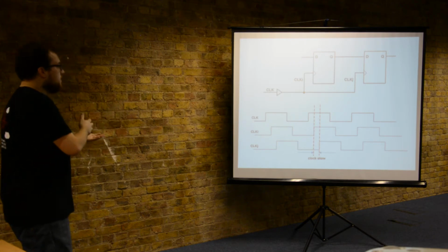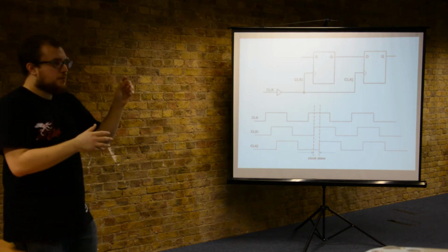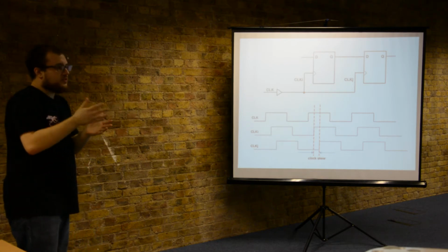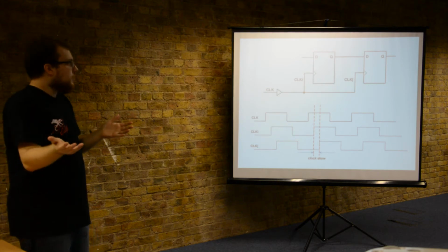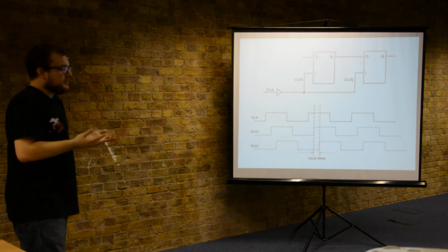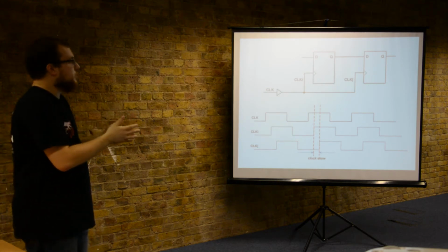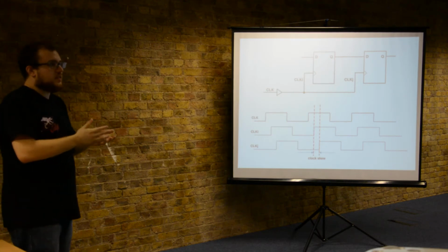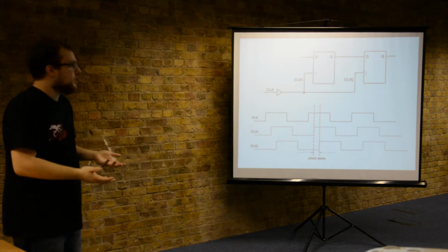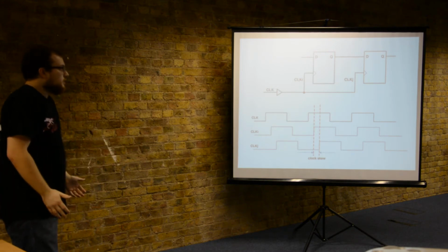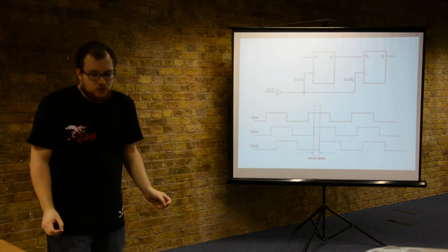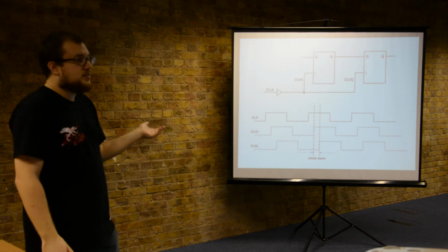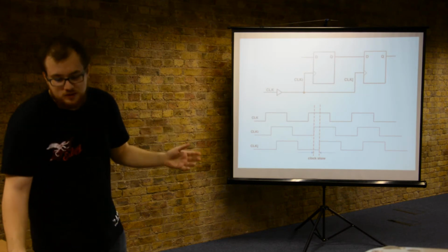What clock skew means is that the clock pulse coming into your system might arrive at different parts of your synchronous logic at different times. Given that in an ideal synchronous system each operation should happen at a clock pulse, if the clock pulse arrives at different points in time, then obviously you're going to have trouble. So if you find that overclocking your 200 megahertz CPU to 500 makes it do funny things, this is probably the reason why. This is the main reason why overclocking doesn't really work after certain speeds.